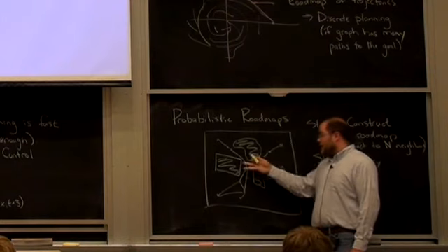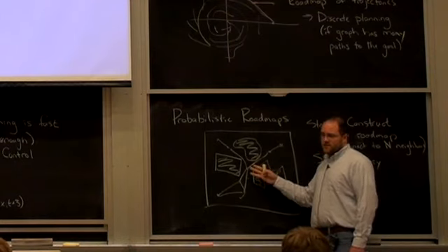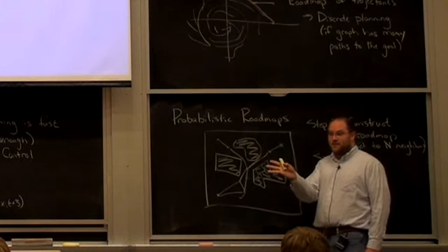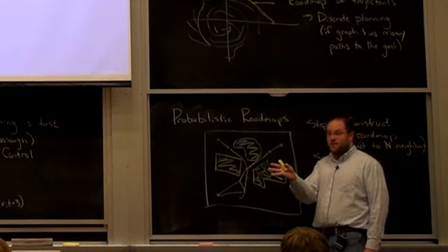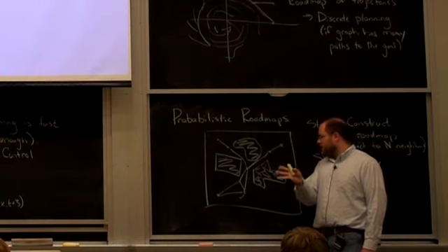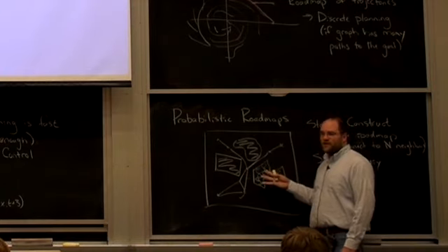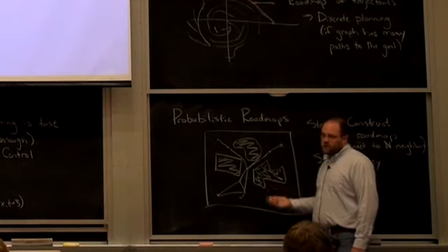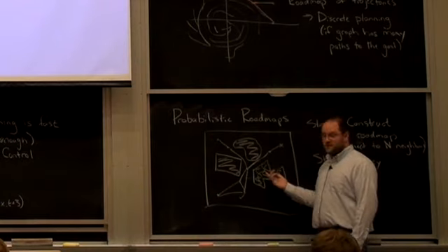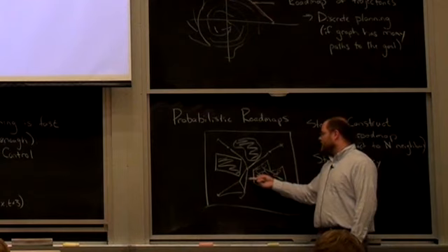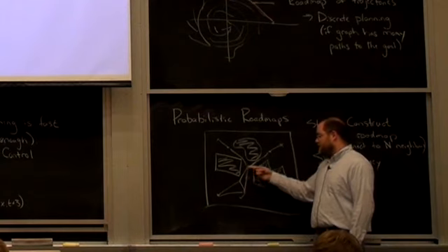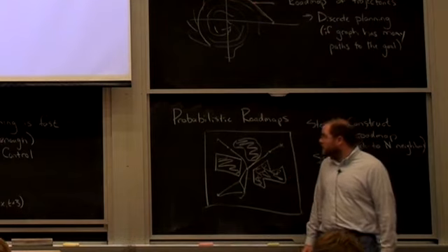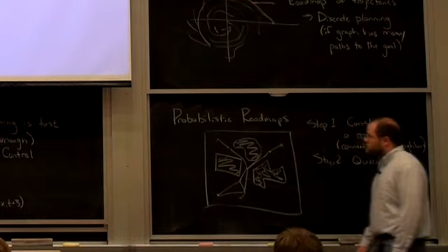And the other thing is if I have a model of how those obstacles are changing, then naively that just adds one dimension in time, let's say, to my plan, and I just have to do a higher dimensional plan. But I think the case you're thinking about is if these things are just moving on their own, I don't have any good model, I suddenly find that I'm obstructed, then again, you could dynamically replan, or you could, by either taking a different path here or making a new edge if you had to. I don't think it breaks the sort of fundamental goal.